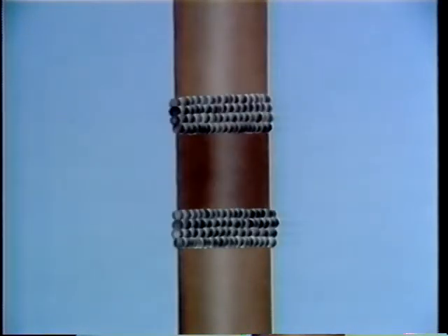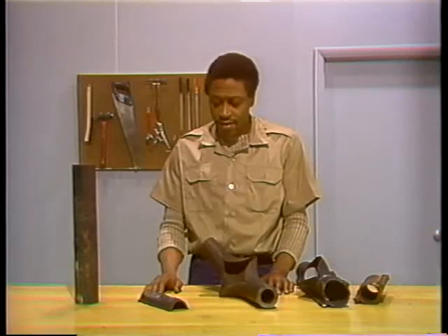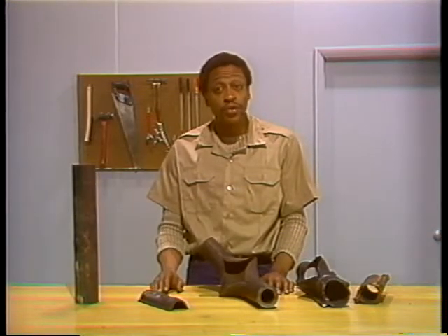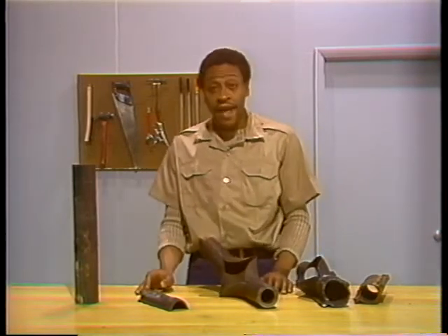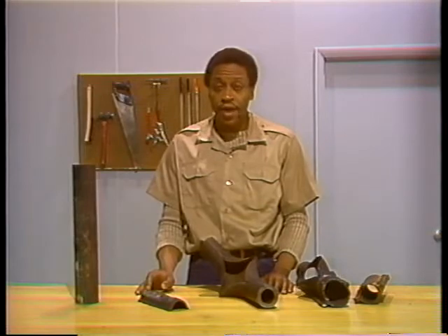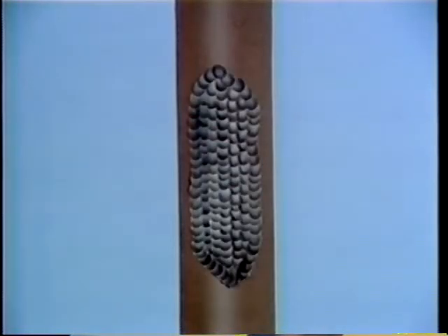The best and most sure way to repair failures and deformities is to replace the damaged section of tube. Although this is the best way, it isn't always possible because it's time-consuming. There are several other methods that are used when there isn't enough time to replace a section of tube. These are cladding, closing a rupture, and window repair. Cladding is sometimes used to repair tube thinning. It's a technique used to thicken and strengthen a tube by applying weld metal to its surface.